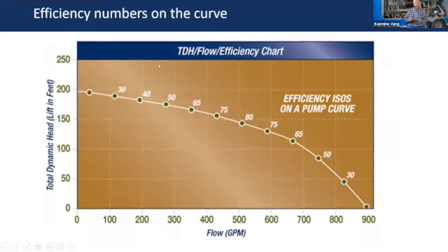And then based on that, we have a pump curve, because you'll see the pump curves I'll have on here. And that pump curve shows that combination of lift in feet and flow rate down here. So for example, this is the pump curve here. At 500 gallons per minute, where it intersects on our pump curve, it's about 80% efficient. That's impeller efficiency, not overall pump efficiency. That doesn't include the motor and stuff. That goes into it too. And about 145 feet of lift.